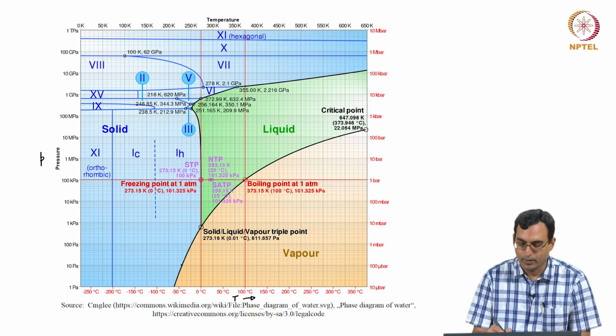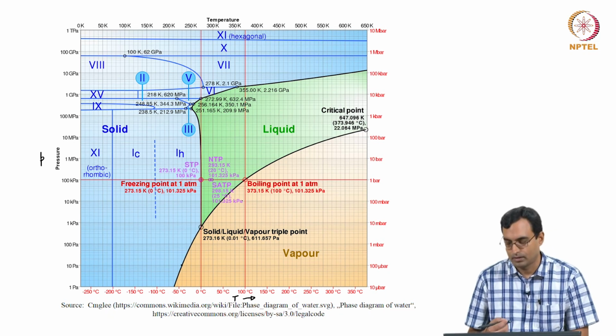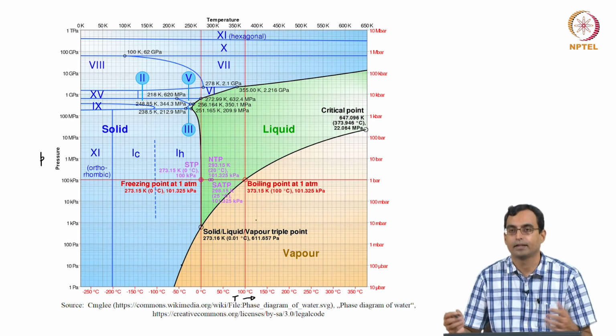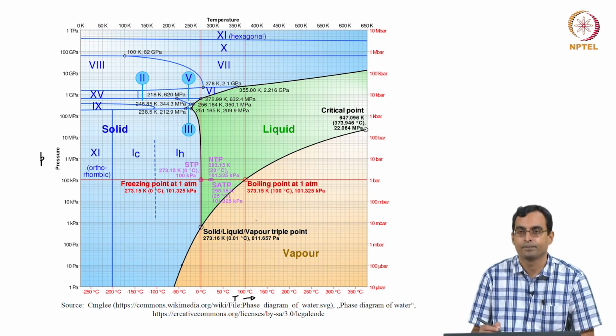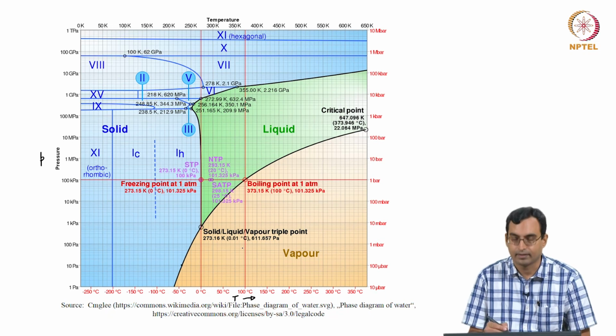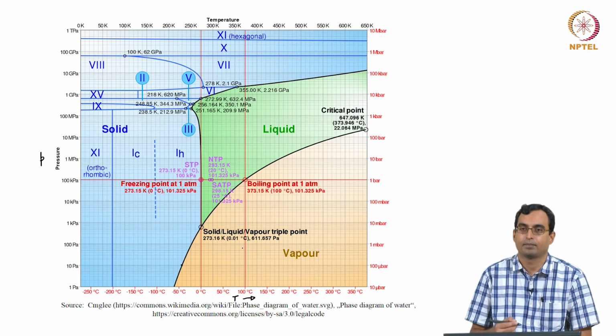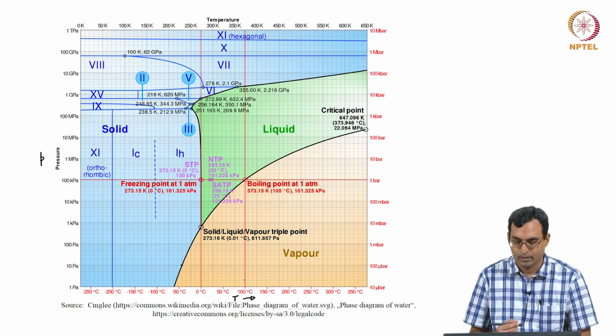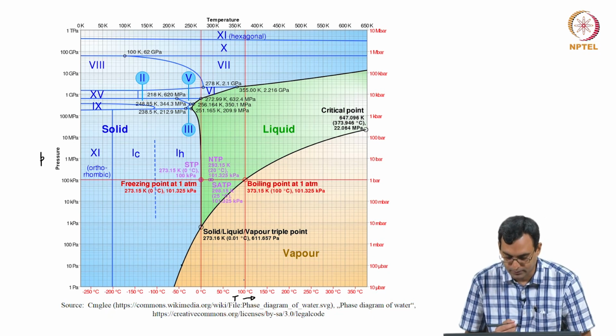And as you come below it, you have vapor whose temperature is still 100 degrees centigrade, but whose volume keeps increasing because the pressure is going down, and you have superheated vapor in all of this region at the same temperature of 100 degrees centigrade, but at varying pressures, at lower and lower pressures. So, that is something which we see.